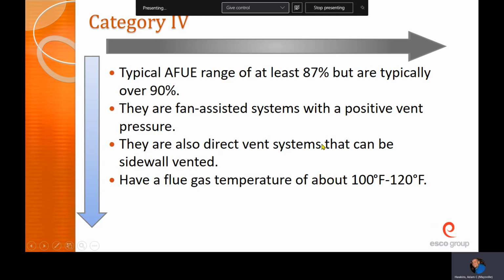Because if you're just running air conditioning through the summer and then your furnace in the winter, ACs, you're going to save some money even with a higher efficiency setup, but they aren't too bad. Anything over 14, 15 SEER, any modern equipment is going to be pretty efficient. But your heating season, that's when you start to see the difference.